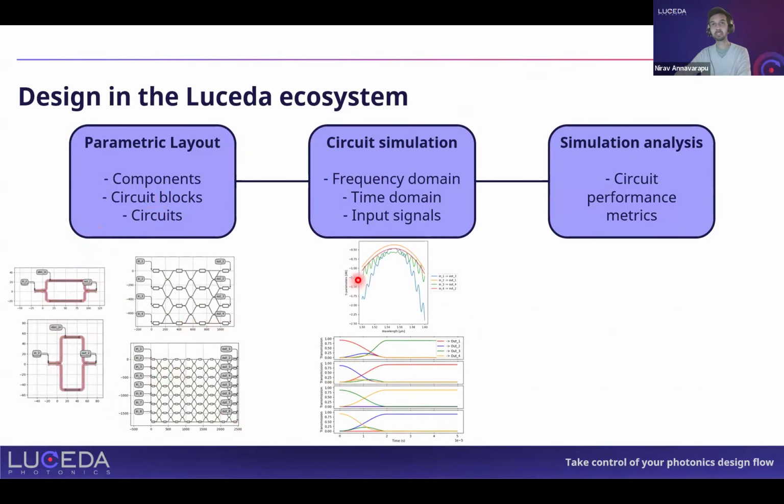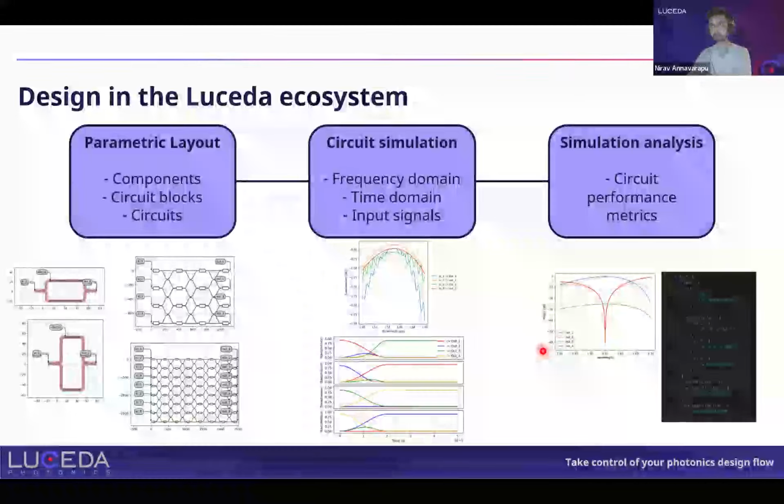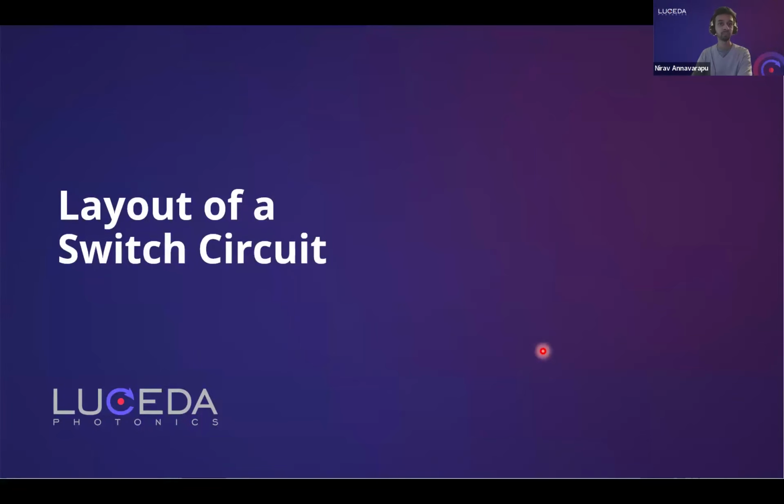And it's possible to do both frequency domain and time domain simulations in IPKISS. You can apply any input signal you want and probe legitimate ports in your circuit. And the user is given control over what inputs he can apply and what ports he can probe without messing with the layout. Finally, you can plug your circuit into a test bench and evaluate its properties with no regard for what is inside. So there's no back and forth between softwares, and it's all seamless and done on one platform. Let's move to the first aspect, which is layout.